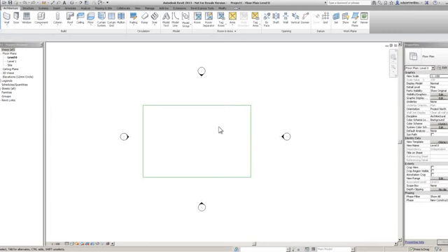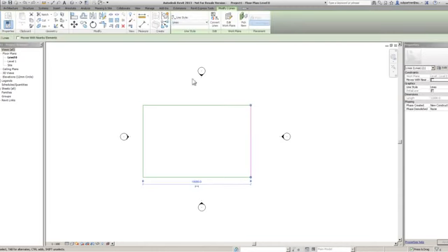Now, because we've got a fairly square shape on the screen, I'm just going to draw a line going through the object so that we can orientate ourselves. So again, I could go model line and draw a line, but I just want to introduce to you another way of drawing something. Basically, I'm just going to pick that line just there. Look at my ribbon, and we have this button just here. It's on our create tab, sorry. And we have just here something called create similar.